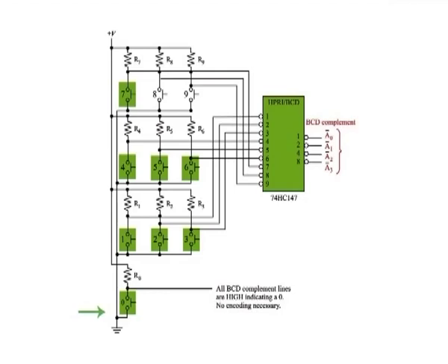depressed. The BCD complement output of the encoder goes into a storage device and each successive BCD code is stored until the entire number has been entered. Methods of storing BCD numbers and binary data are covered in later lectures.